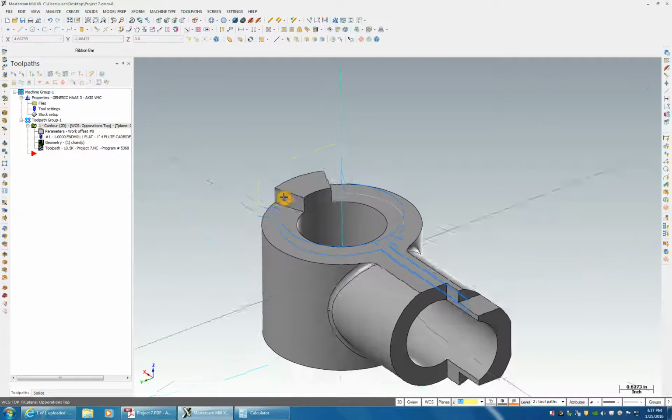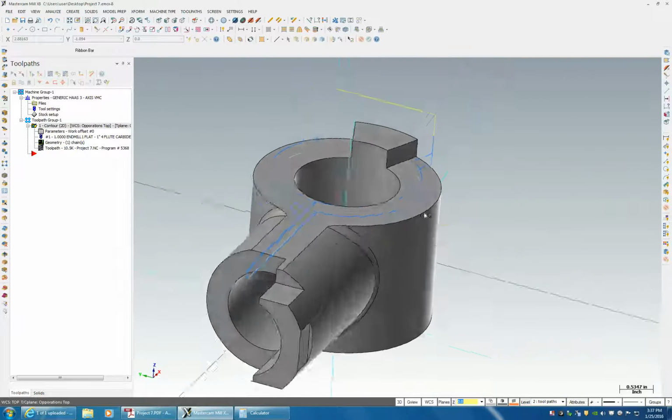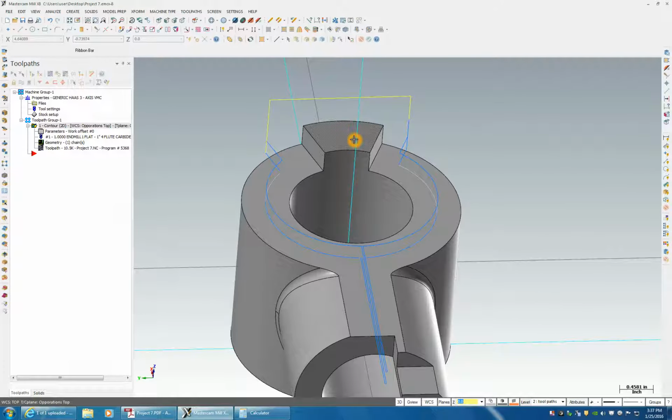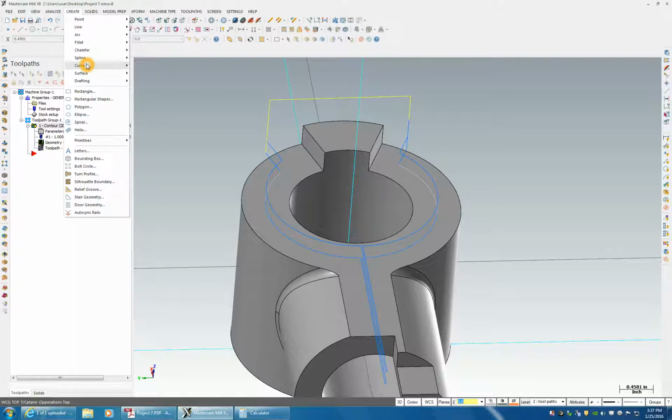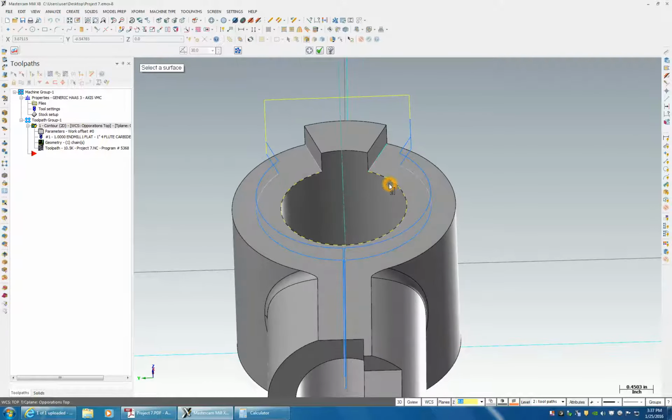And we can do this in one depth. So what we're going to do is I'm going to duplicate this CAD, we're going to connect the two and round them off. So create curve on one edge, this edge here and this edge here. Now we're going to extend them until they touch. We'll now trim them back, and I will also give them a fillet of 1/4 inch is fine.